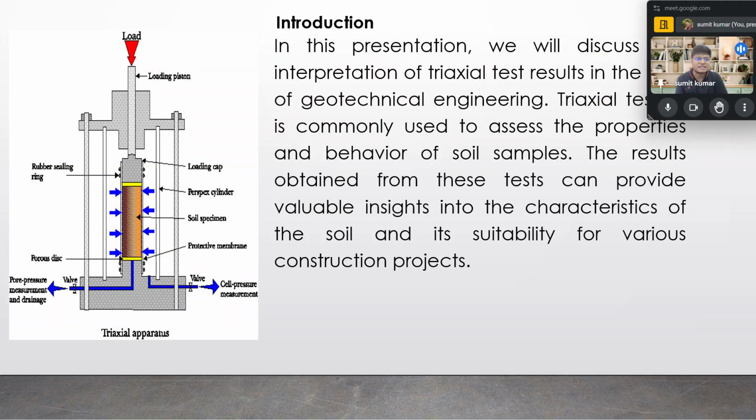found how the triaxial test setup works, what the back pressure is, and how the pore water pressure and the different conditions are achieved. The results from the triaxial test can provide valuable insight into the characteristics of the soil and the suitability of various construction practices, as we come to understand through our study, right?